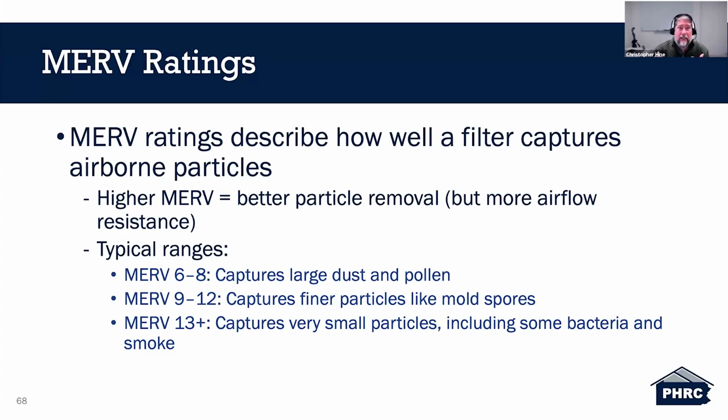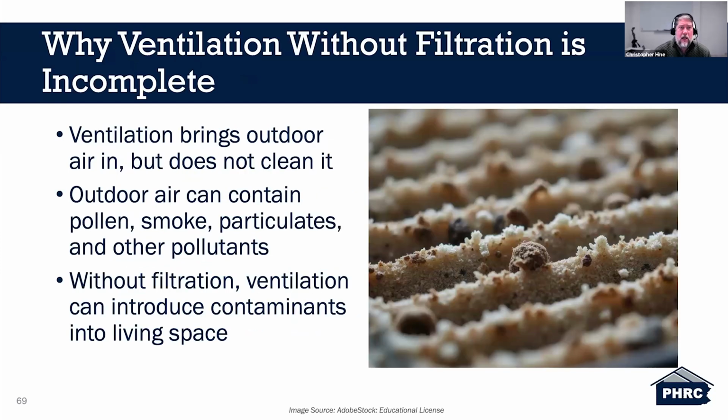That will dramatically increase the static pressure of that system, which could have an adverse effect on the system as a whole, primarily the mechanical part of it, the fan. So if you have any questions on that, I would highly encourage you to reach out to an HVAC technician to see if the system that you have does allow you to increase the MERV rating of the filter without an adverse effect on the system.